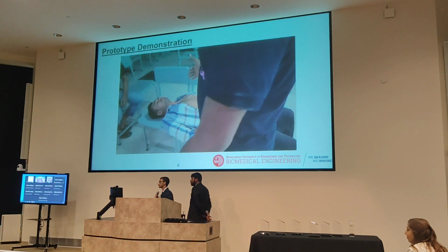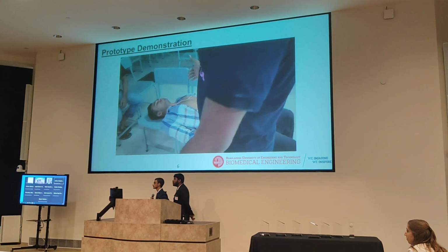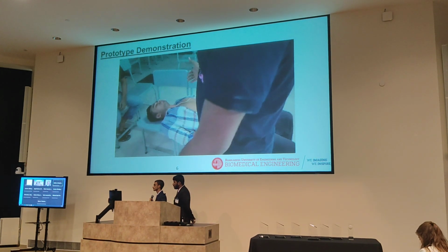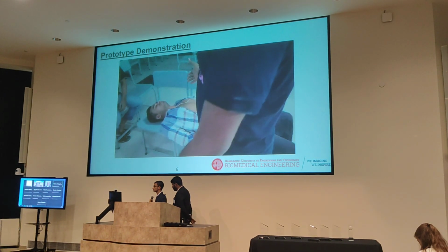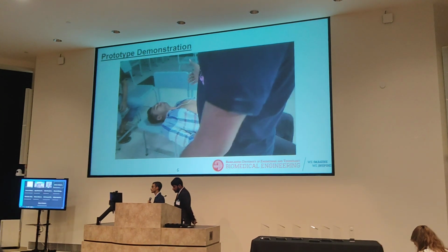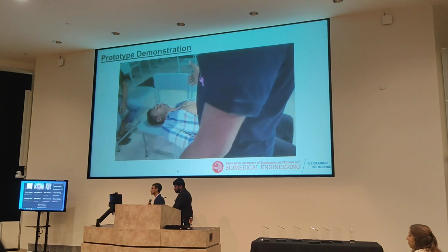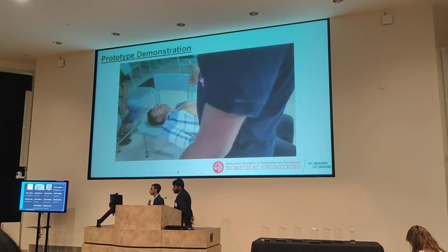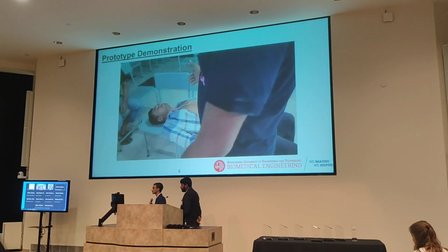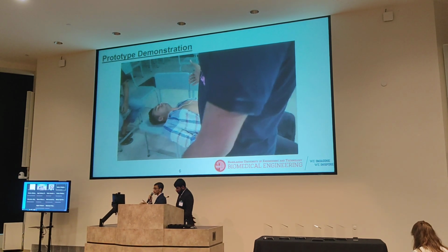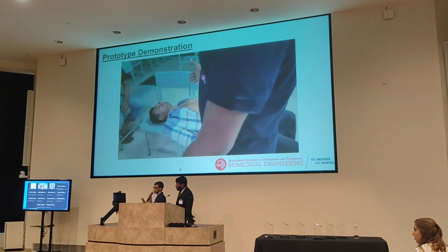So, no, I think what she was asking is, are you able to shock with the leads? Because currently with AEDs, you detect the rhythm with the pads, and you apply the shock so that nothing ever comes off or on. But what you have currently, you have the leads to detect the arrhythmia. Do you need to pull those off before you use the paddles? No, actually, there is a protection circuit, so it's not needed.